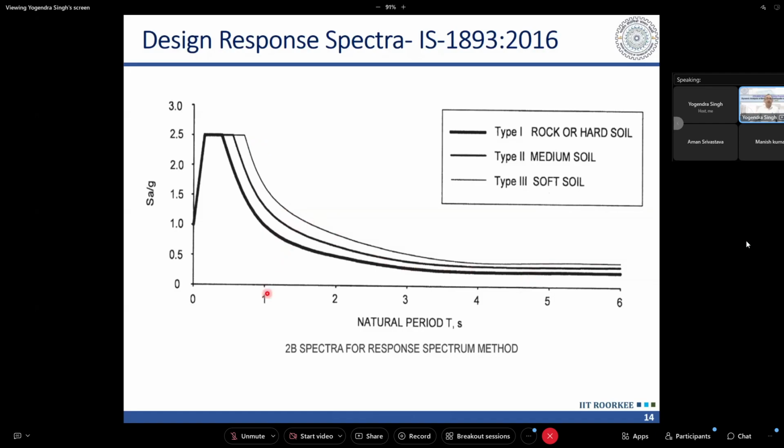Here we don't see any specific peak in the long period, but we see that the whole of the response spectrum has been increased, because the period at which that peak is going to occur will depend upon the local site. It will vary from site to site. So this response spectrum tries to take that into account in an average sense. But if we are expecting large soil amplification to occur, we should perform a site-specific analysis for amplification.